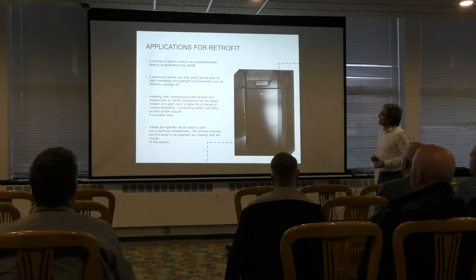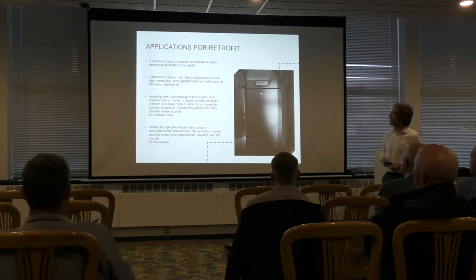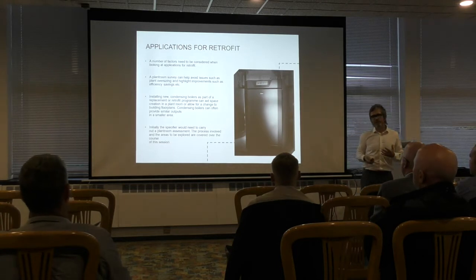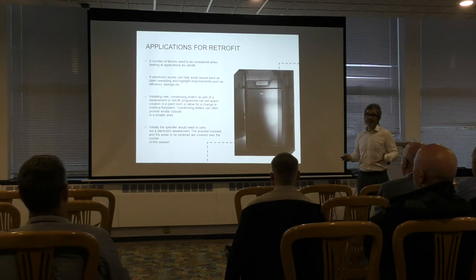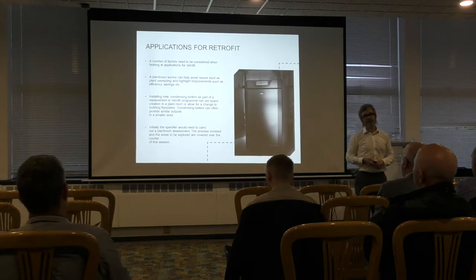But when we look at the applications for the retrofit, there are a number of factors we need to consider. We say that a plant room survey can help avoid issues such as plant oversizing. What we mean by that is it was probably common practice maybe 10, 15, 25 years ago to oversize plant. You'd do 100% run and standby. Now we do things slightly differently, so potentially we could look at reducing the size of the boilers we're putting back in.